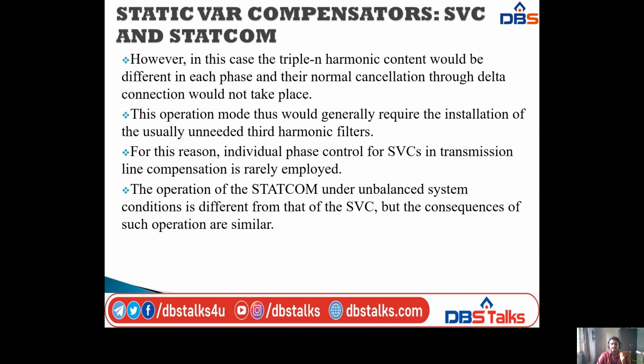For this reason, individual phase control for SVC in transmission line compensation is rarely employed. The operation of the STATCOM under unbalanced system conditions is different from that of the SVC, but the consequences of such operation are similar for both.